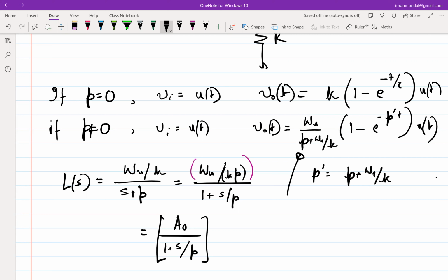So his question is about this expression. If you ignore the value of K, it is indistinguishable from an RC low pass filter, right? It's 1 by 1 plus something. So then what's working? Firstly, if you use a first order RC low pass filter, you cannot get a gain of K. But if you use unity gain feedback, K equal to 1, then it seems like an RC low pass filter.